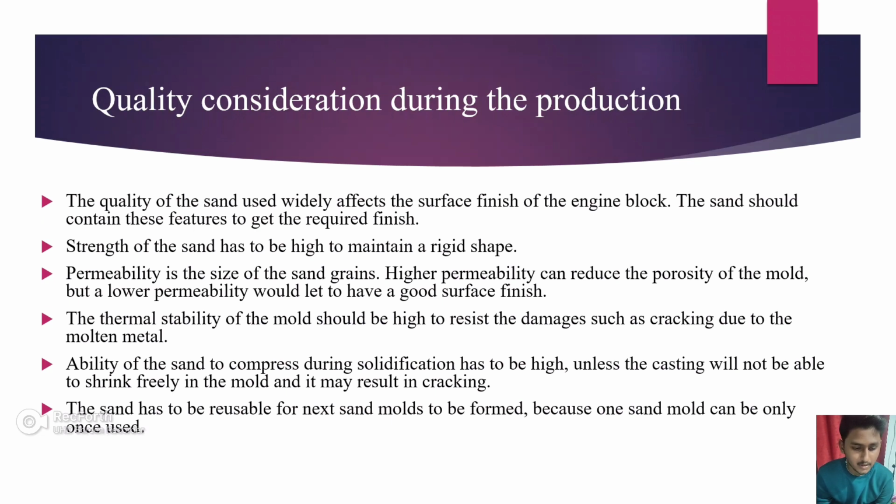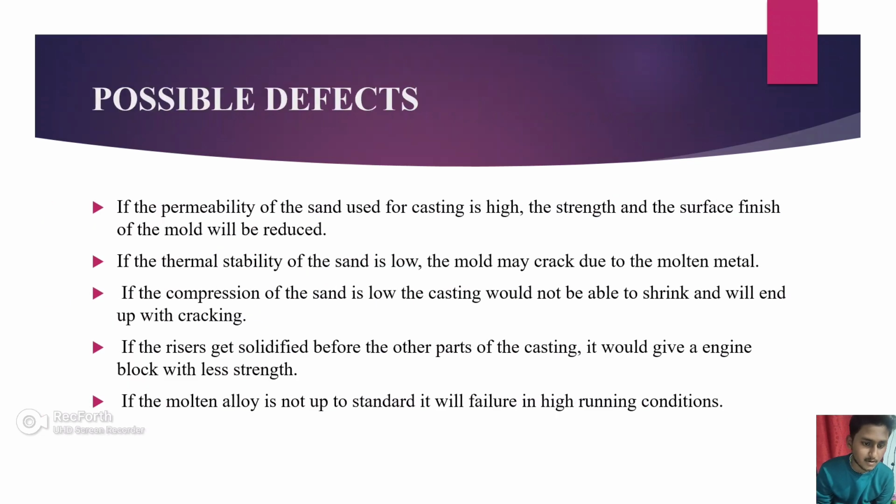The thermal stability of the mold should be high to resist damage. The ability of the sand to compress during solidification has to be high, otherwise the casting will not be able to shrink freely in the mold and it may result in cracking. The sand has to be reformed because one sand mold can be used only once.